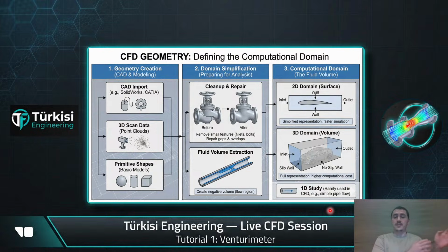You can search for 1D modeling, for example 1D modeling for heat transfer, or 1D modeling for cooling of an electrical motor. It's very useful. Sometimes you have engineers working only in 1D modeling who are not skilled in CFD, but it's more useful for the company to simulate the complicated system with 1D empirical correlations to predict what happens, and it gives a very good prediction. So keep in mind that there are some alternatives to CFD.